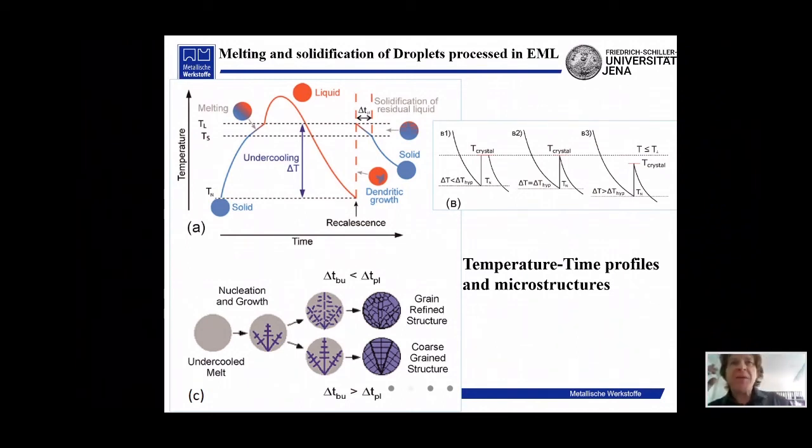What does it mean, adiabatic temperature? It means that with reaching the adiabatic temperature, TN will be consistent with the adiabatic temperature. We don't need outer removal of the heat released during solidification. Undercooling is so high that it accumulates all the heat released during solidification. Because of this, we don't need to have boundary or outer removal of the heat from the sample.